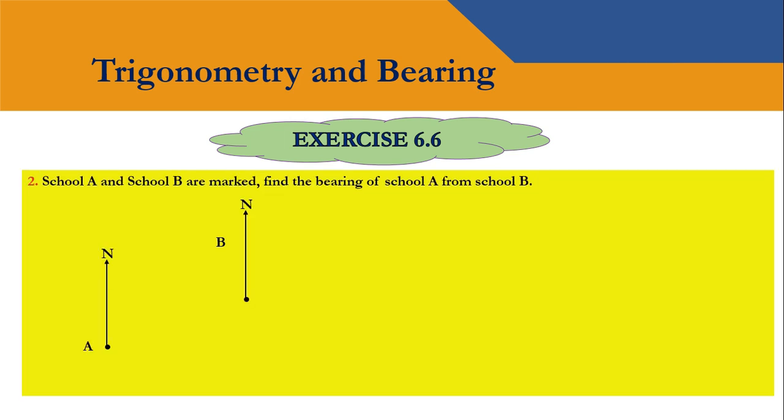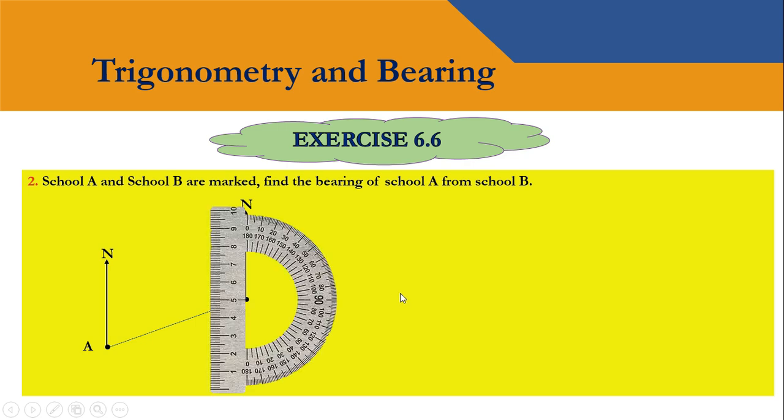Now moving toward question number 2. School A and school B are marked. Find the bearing of school A from school B. First we have to construct a straight line connecting A with B. Now place the protractor on B because we measure the bearing of school A from B. To measure the bearing from B, we have to measure this angle which is 180 degrees.